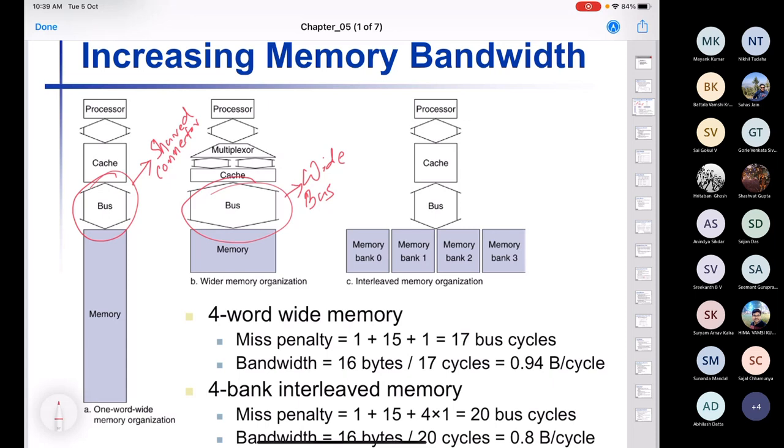They would access only 1 word at a time from cache memory, and they will store it into their registers. Then maybe they will fetch the next word and again store it in the register. That's why from a wide cache, you might have another address multiplexer which selects which of these cache memory words will be stored and finally brought to the processor.